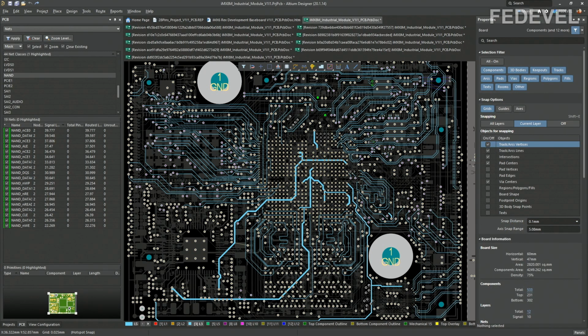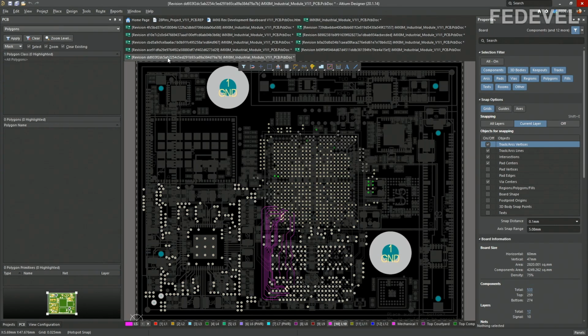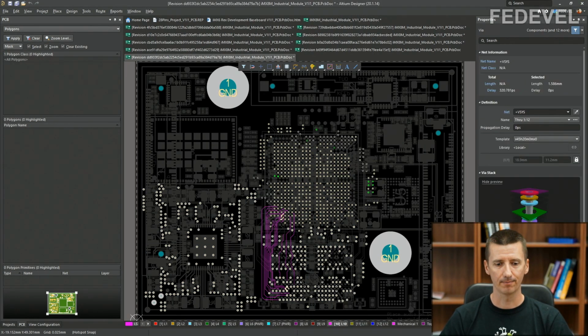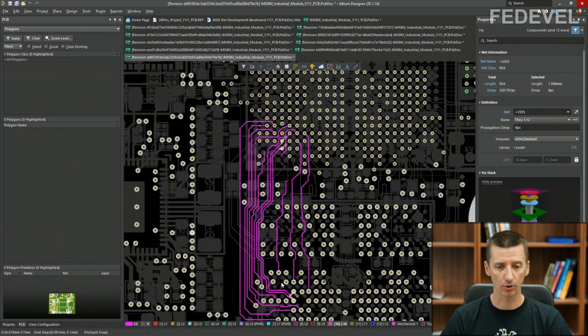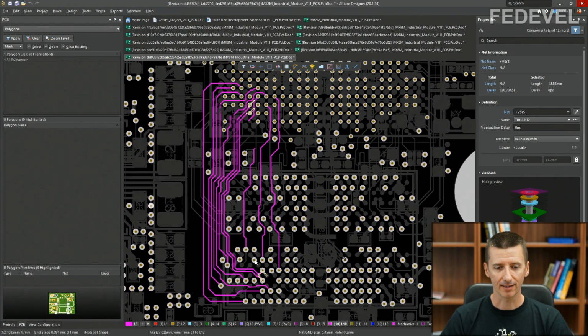First, we are going to have a look at the memory layout. This is what I have received from the junior hardware design engineer. This is the preliminary DDR4 memory layout between the processor and the memory chip. And this is maybe not really what we would like to do when we are doing a preliminary layout. What do you think? Why? What would we like to improve here?